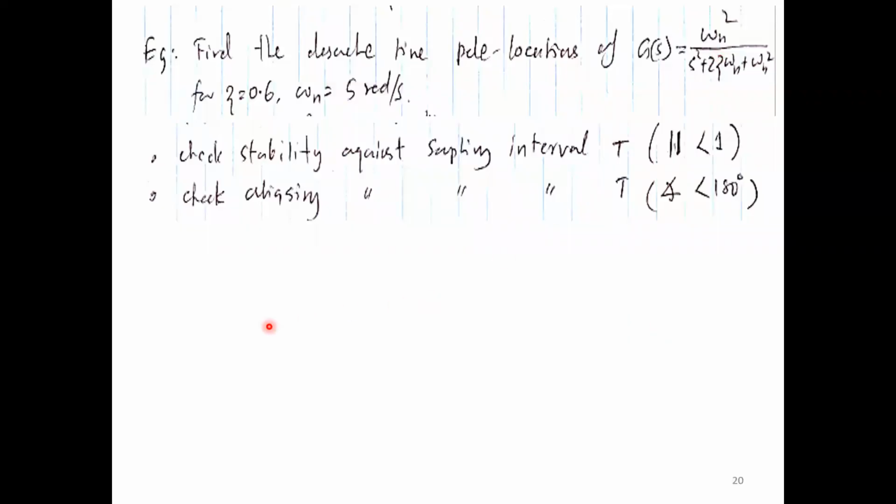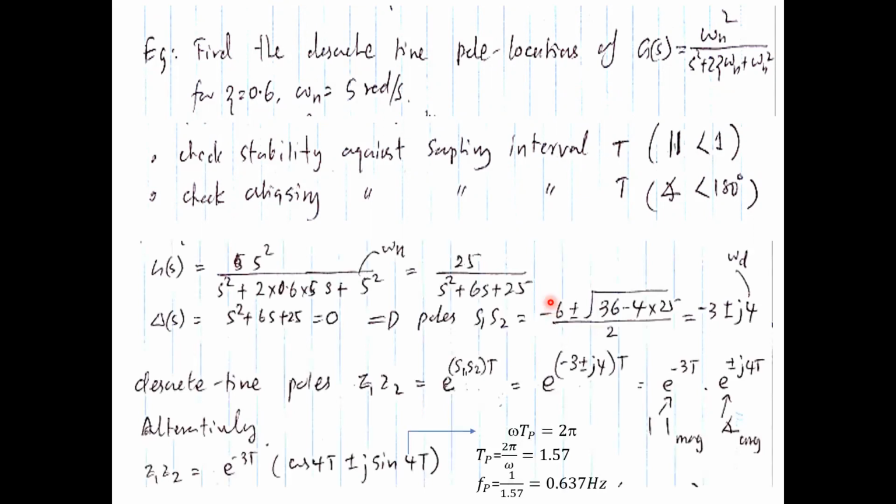All right. You may check your answers. So it's a simple sum. You have the transfer function, which is this one, generic second order plant, where the natural undamped frequency and the damping ratio are both given as 5 and 0.6. You just write the transfer function and substitute 5 here and 0.6 over here. So this is your transfer function.